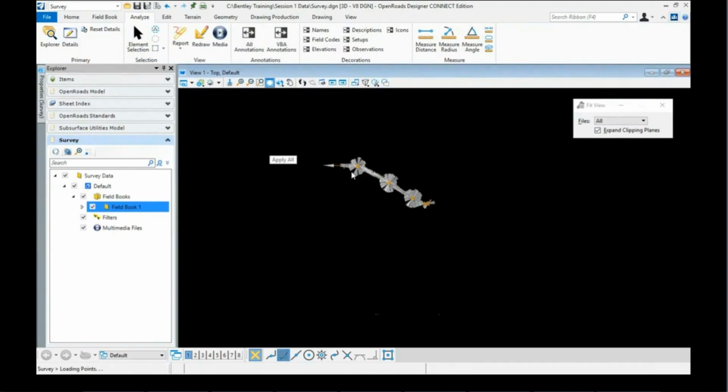reducing all that raw survey data. It's pulling in the angle rights, the slope distances, the zenith angles to plot those points in the file for me. It's looking at the feature codes to tell it how to draw, and it's looking at the linking codes to build the strings for me. And we'll let it finish up here for a second.